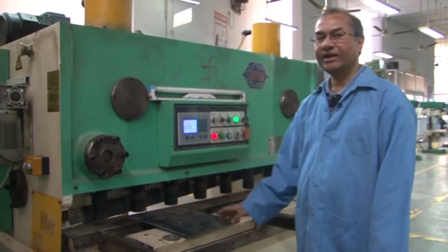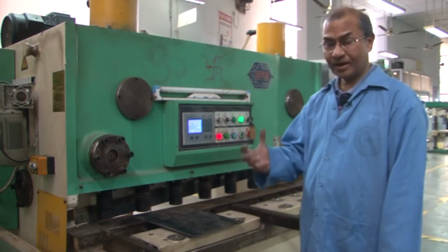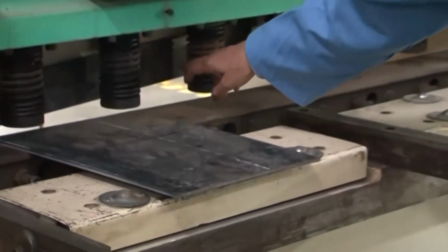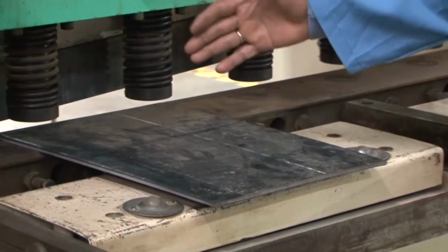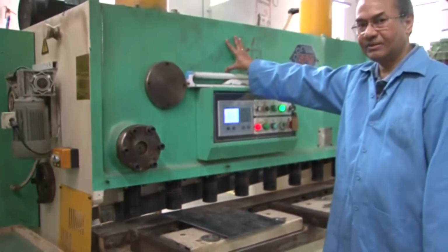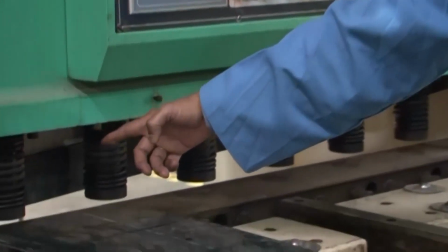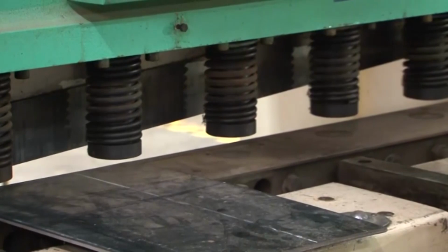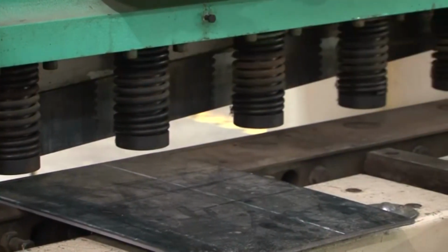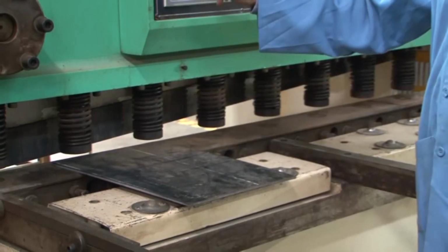So, this is a hydraulically operated shearing machine, and since it is hydraulically operated, you understand that the strength or the load carrying capacity of this machine would be very high. Here you can see that this is the cutter which works on the principle of a guillotine, and it moves downwards, and this is moved by the hydraulic cylinders inside the chamber here inside the machine. As the machine is on, the shearing plate or the tool cutter will be coming down, and prior to that we have to set the distance in the x axis, what is the length that you would like to cut. Of course, up to 4 feet of width can be cut here, and length you can adjust by adjusting this value.